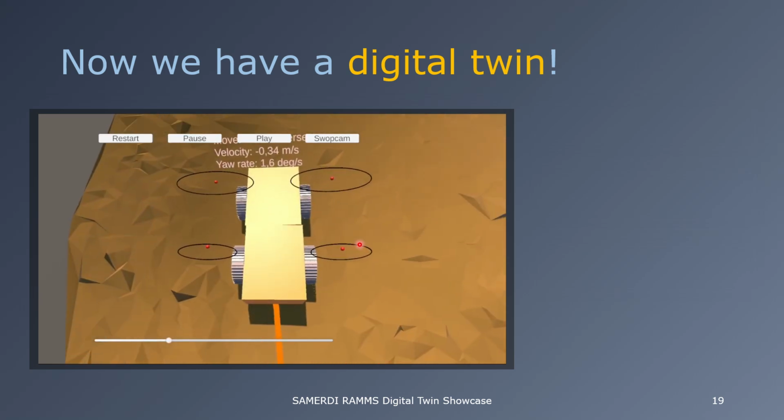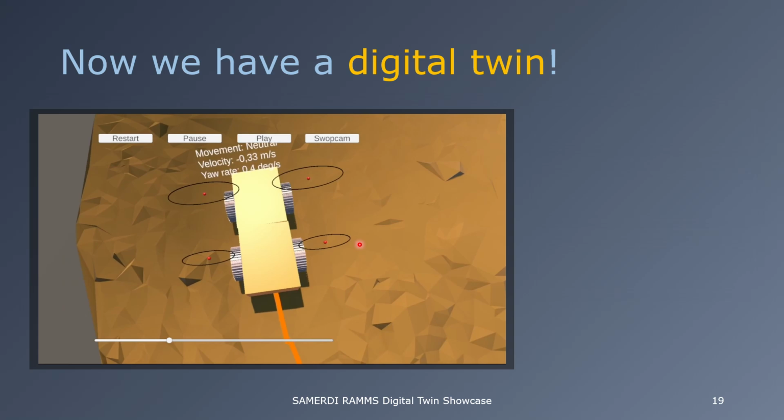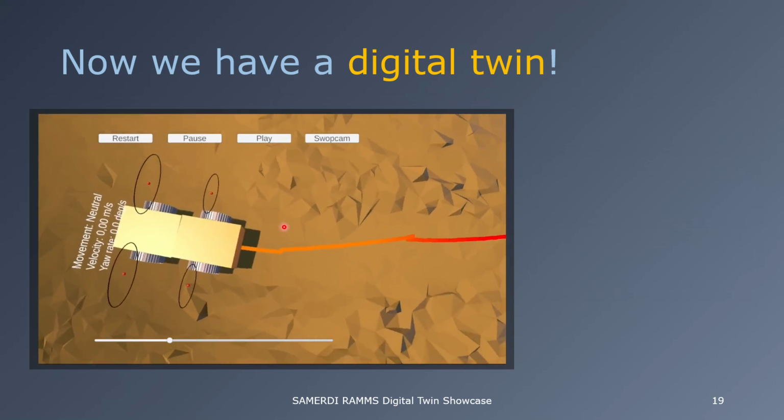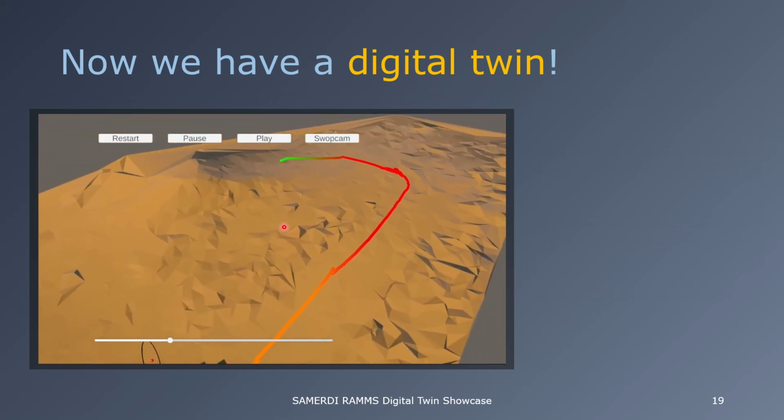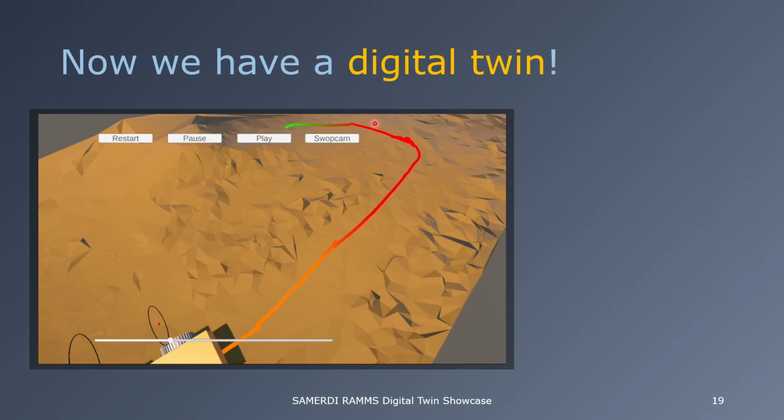The other thing I'd like to draw your attention to is that part of this modeling process, we also got what we call a motion resistance coefficient. And this is what I plotted on this trajectory. So what we can see is when the vehicle traveled downhill, it was actually quite a low motion resistance, or the green values. And then round about here, the vehicle got stuck in the mud. So you can see there's quite a high motion resistance.